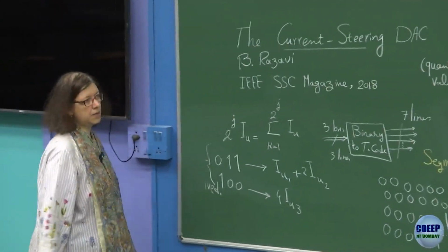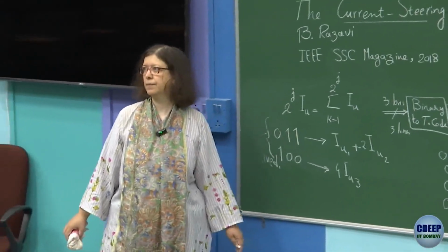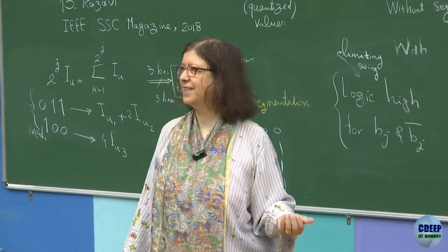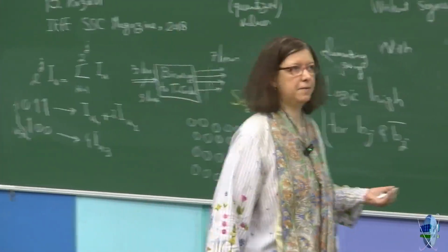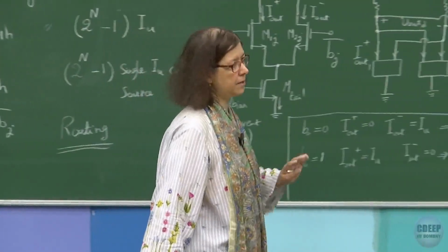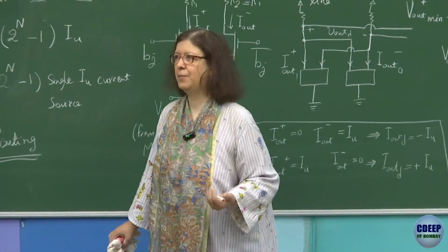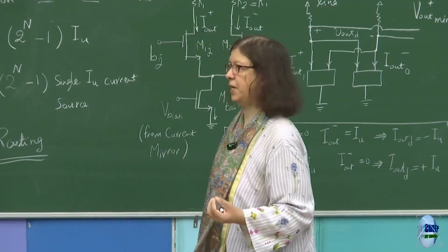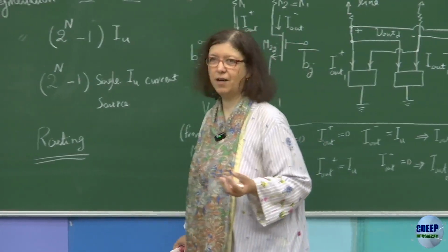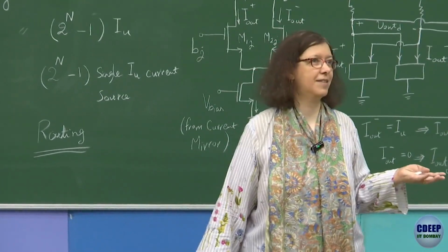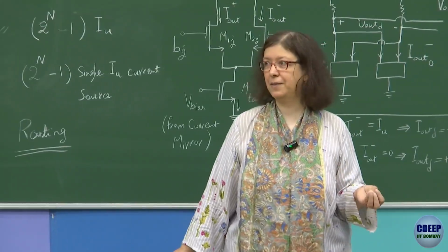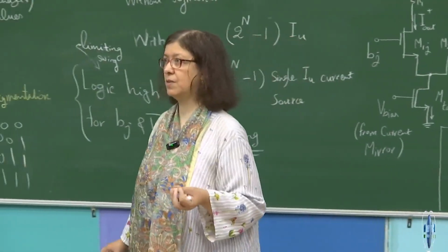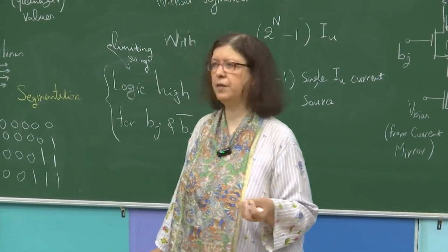High speed is also like high frequency. What's the difference between high speed and high frequency? In the technical domain, there is a difference. That's why high speed and high frequency are used as two separate domains. Applications also are different. In high frequency, as the name shows, the frequency is high, but it could be a single frequency. Therefore, you have a narrow bandwidth, not necessarily a wide bandwidth. Your focus is on the frequencies only, but these frequencies could be in a very narrow band.